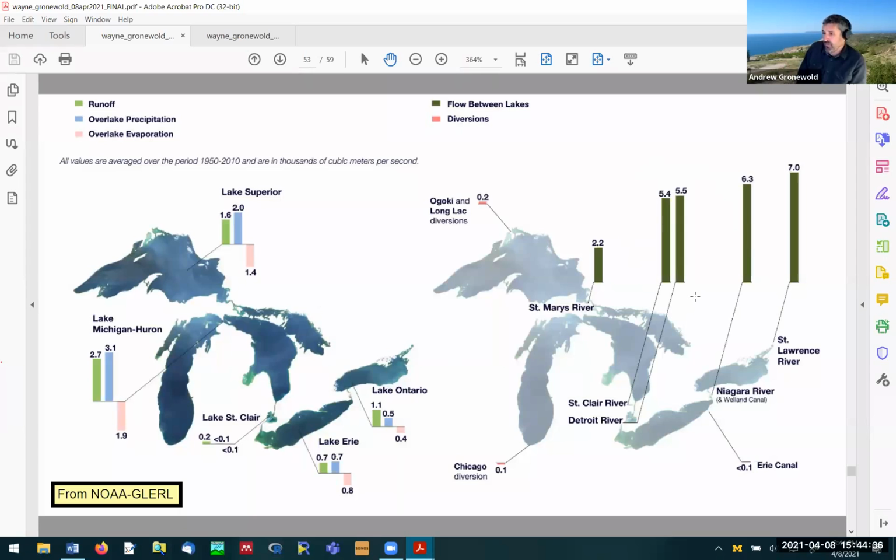Well, one way is to continue advancing the monitoring infrastructure, right? There are several different ways to monitor flow in rivers and streams, some of which involve old mechanical flow meters. For a lot of the historical record, that's all we had. But some of the new techniques involve ADCPs, acoustic Doppler current profilers, or current meters that can provide a more accurate reflection of what's happening in the water column. Those are being put online right now. But I would argue, even with those measurement techniques, there are still some uncertainties and variabilities.